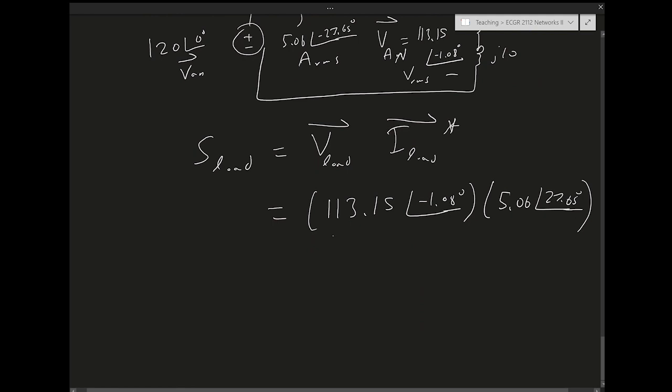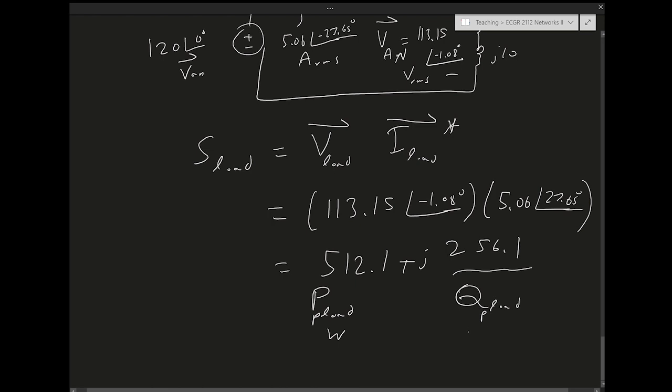If I multiply those two together, I end up with 512.1 plus J256.1. So this is the power at the load for a single phase, right? This is in watts, 512 watts, and this is the reactive power at the load, 256.1 VARs.